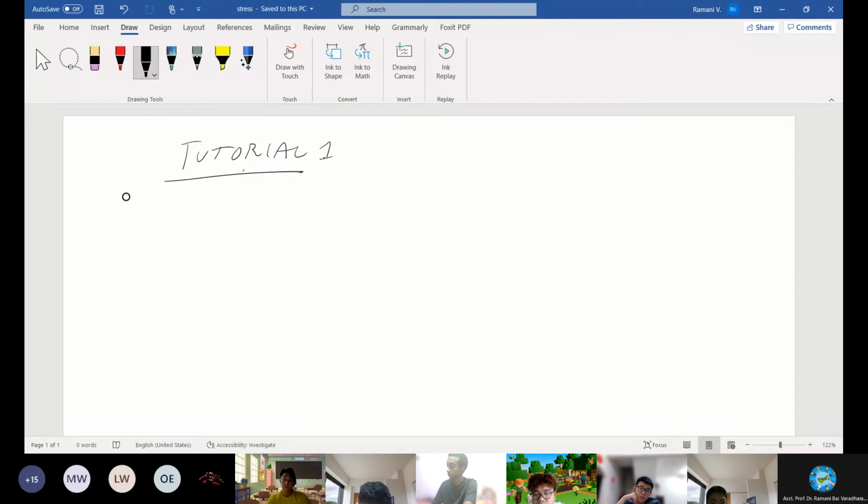The bar has a constant width of 35 mm and the thickness is 10 mm. Can you hear me? Okay, the cross section is given. You are given a bar that is supported, or just held by a certain type of loading, at the ends. The cross section is 35 by 10 mm. Determine the maximum average normal stress in the bar when it is subjected to a loading.